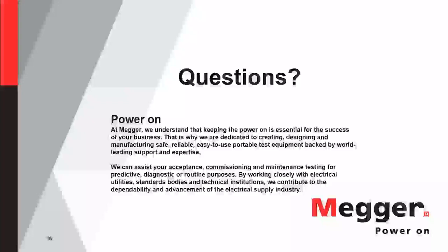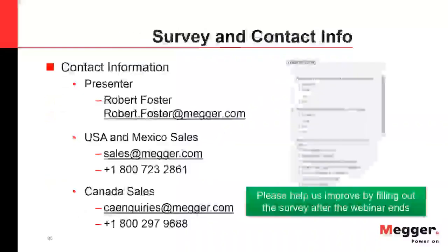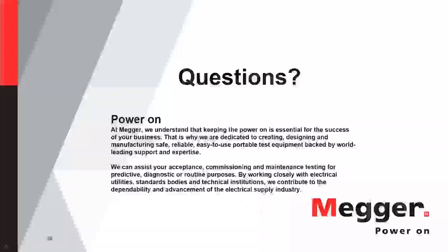Not generally. What I found is that it really doesn't depend on the type of breaker. I've seen where you use a linear transducer on a live tank and a linear transducer on a dead tank. I've seen people use a rotary transducer on a live tank and a rotary on a dead tank. It really just depends on the manufacturer. You can even look at that case study I did with Siemens. The manufacturer recommends using a linear, but we used the rotary and we were able to get very good results. So it doesn't really matter.